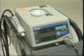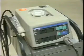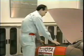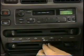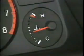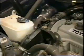Now, let's see how to adjust the idle speed and mixture. You should use a CO meter to do this if possible. First, in order to adjust the speed mixture properly, we must make sure that the following conditions are met. Make sure that all the electrical accessories are turned off. Check to see that the transmission is in neutral. Make sure that the engine is warmed up. Confirm that the ignition pin is set properly.